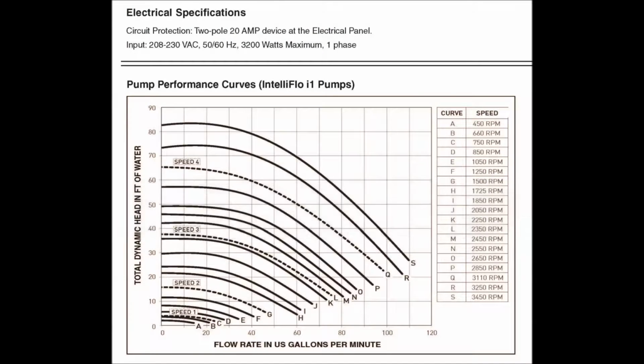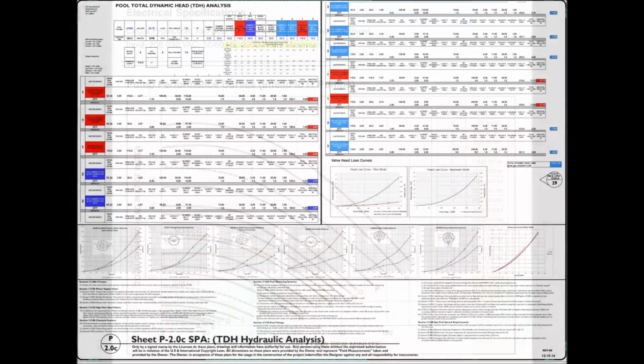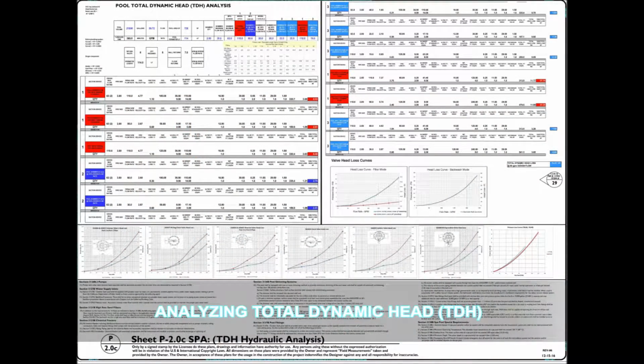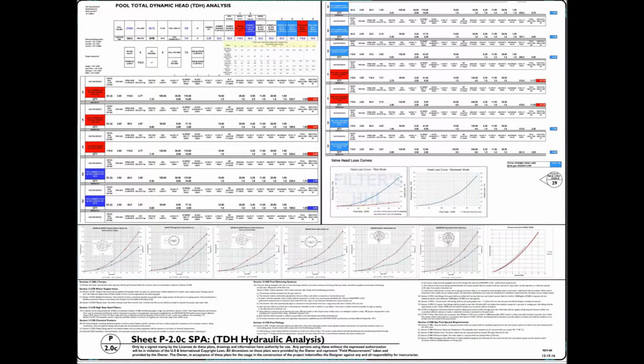Yet some interpret a pump's output as total dynamic head, although this is incorrect, and this misnomer is widely applied to the measurement for a pump's head-foot output. While it is true that the pump's head-foot measurement relates to the selected pump's ability to overcome the system's TDH hydraulic head loss conditions, the use of this shortcut terminology may lead to confusion for what a TDH analysis actually